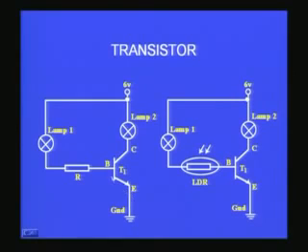This voltage is nothing but the forward biased base-emitter junction, and you know for silicon the forward bias junction voltage is around 0.65 or 0.7 volts. So we almost always know that this voltage VBE for a silicon transistor is about 0.7 volts. If the supply is about 6 volts, then 6 volts minus 0.7 is the voltage available for passing current through the lamp and the resistor. If you neglect the resistance of the lamp, the current is decided only by R. So the lamp will glow very dimly because of the presence of this resistance.